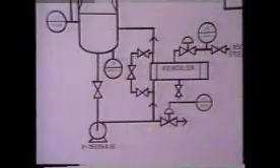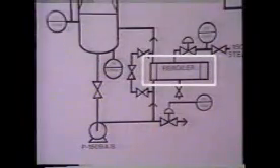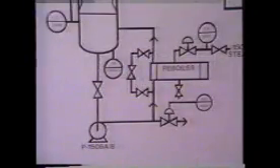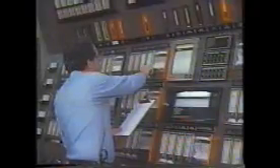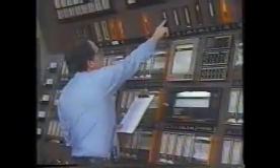Once there is mixture circulating through the reboiler, heat can be applied to the reboiler. To do this, the inside operator manually adjusts a temperature controller which opens a valve that allows steam to go to the reboiler. Now, since the reboiler is heating up the mixture, some of the mixture vaporizes when it's recirculated back into the column. This means that the level at the bottom of the column will drop again. Therefore, the inside operator adjusts the flow of feed mixture into the column to keep the level the same. He may need to adjust the feed several times to keep the level constant.